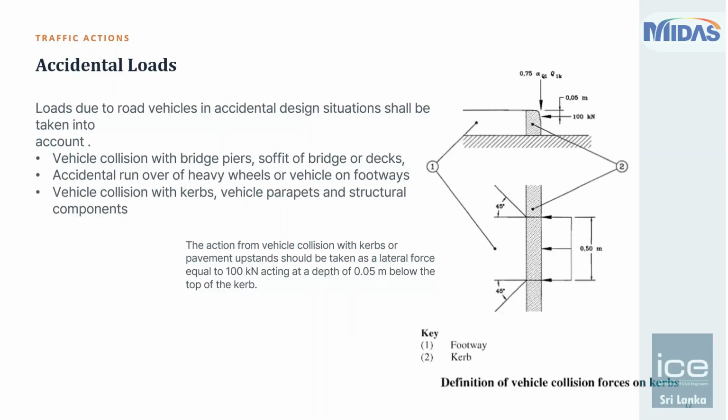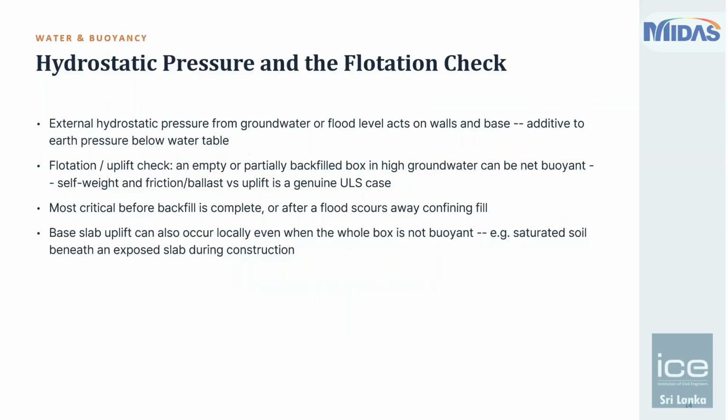But there's a possibility that your vehicle might run over the footway, which has not been designed for that live load arising from the vehicular movement. Okay, because vehicular movement is supposed to be on the carriageway instead of the footway, but in accidental cases you will get that load. Okay, also because we have in this model not considered any uplift, but we must always, if the hydrological or geotechnical report states that you have a water table above the base of the bottom slab during the design life of the structure, then we must always account for the hydrostatic pressures arising from that water table.